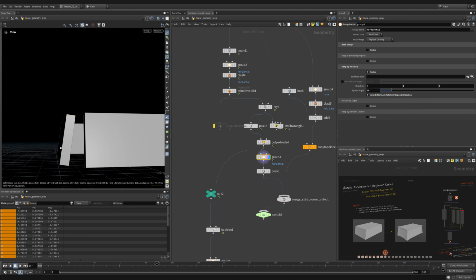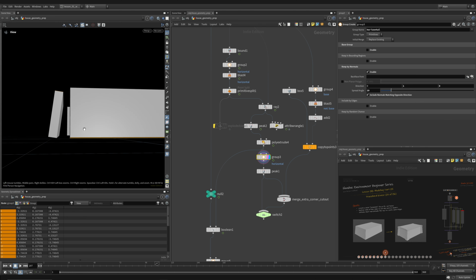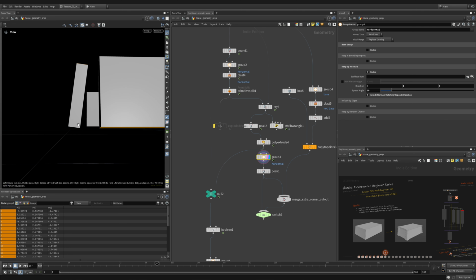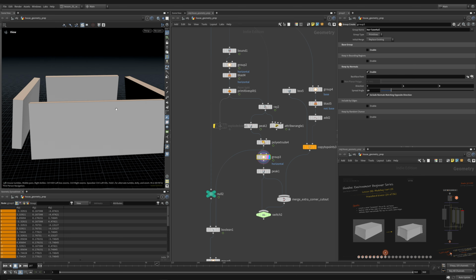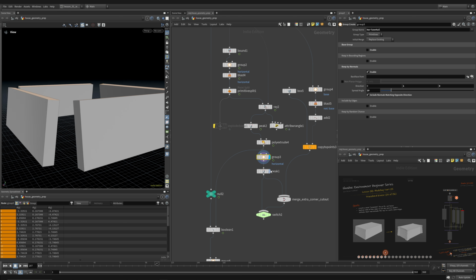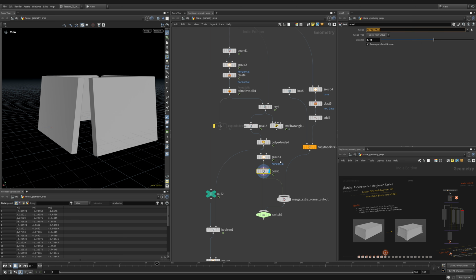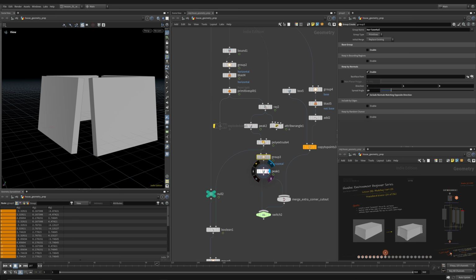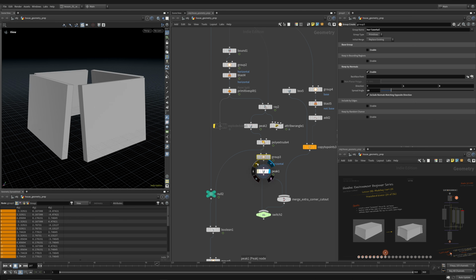So I pick up and down objects and I use a spread angle of 20 degrees. So I can get these slightly slanted normals here. They're not directly down in -1 or +1. They're within a margin of error of 20 degrees for those angles, and we'll group those together. And then again, we'll peak, but just this horizontal group, which we've just created here. So this moves those normals, or these object faces, these primitives, in the direction of those normals.